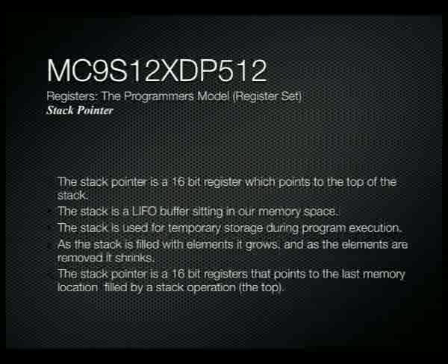The stack is a LIFO storage structure, so it's last in, first out. It's effectively like, as the name suggests, a stack. As I said, it's used for temporary storage during program execution. As we fill the stack, it grows in size, and as we remove elements, the stack shrinks. The stack pointer is a 16-bit register that points to the last memory location filled by the stack operation. So it effectively points to the top of the stack. To give you an example